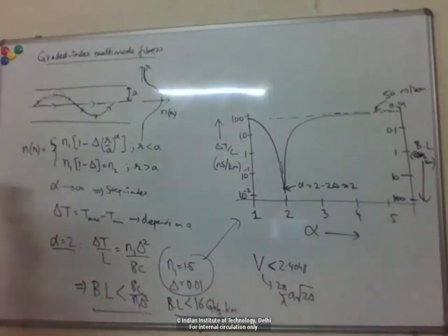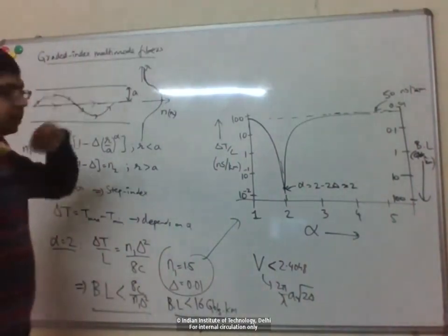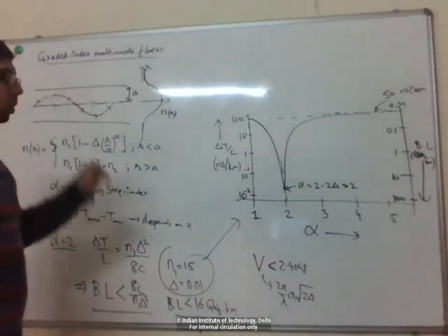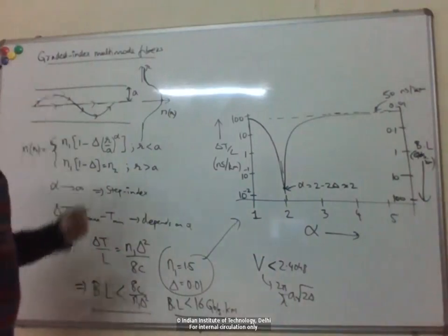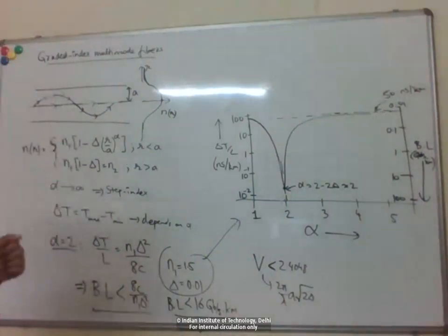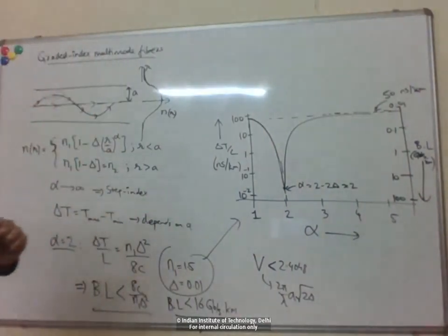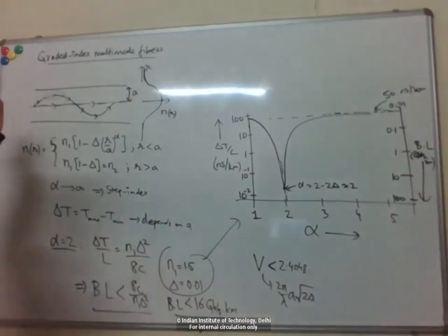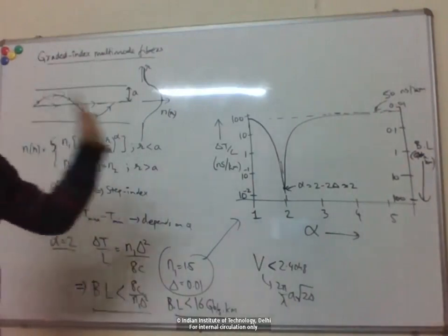So then we eliminated this intermodal dispersion altogether, right? So now there's only one ray, right? This ray picture works only in the multi-mode case where we can treat different modes as different rays, right? But this is an approximate picture. The exact picture is the wave picture. You solve the Maxwell's equations, and for single mode, you just get one mode, right? So there is no question about different rays taking different paths or anything. There's only one mode.